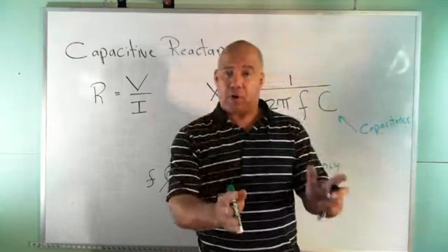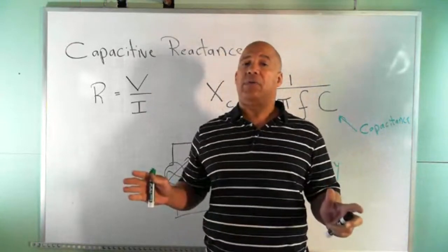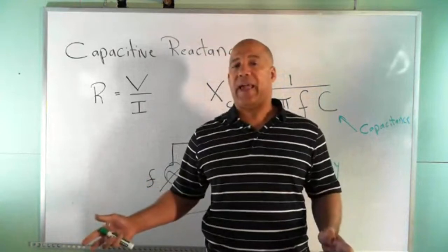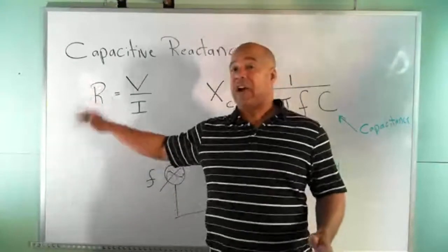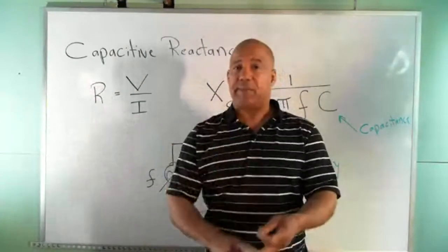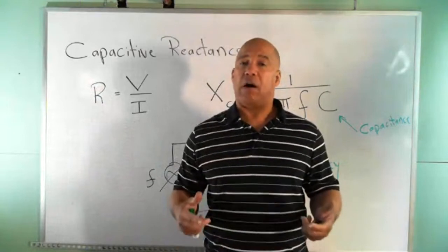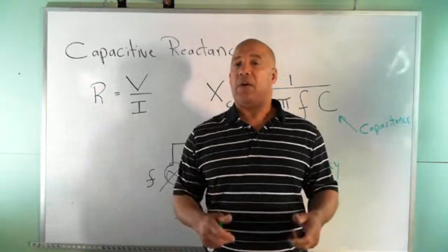You can use a multimeter like the one we use in class, but you can also use an oscilloscope, and you'll be introduced to the oscilloscope in the lab. The oscilloscope has the ability to measure those other values we talked about, peak to peak. But a multimeter always measures RMS. So any meter you use, you get an RMS value.